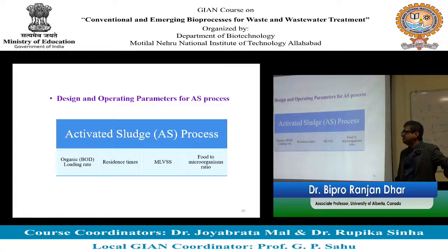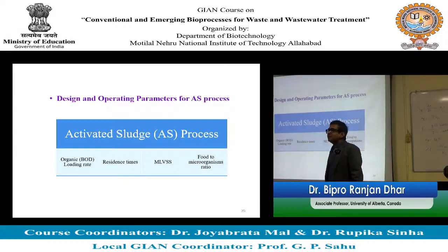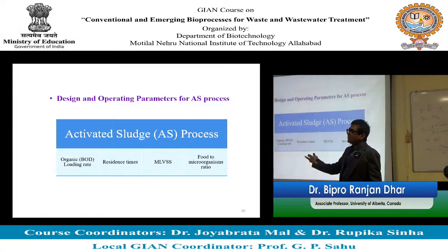So how do we measure this MLVSS? MLSS I know how to measure. MLSS is total suspended solids, right? We take a sample in a measuring cylinder and allow it to settle for 30 minutes. Then we know the sludge index, something. No, it's actually sludge volume index. That is not this one; it's more for settleability.